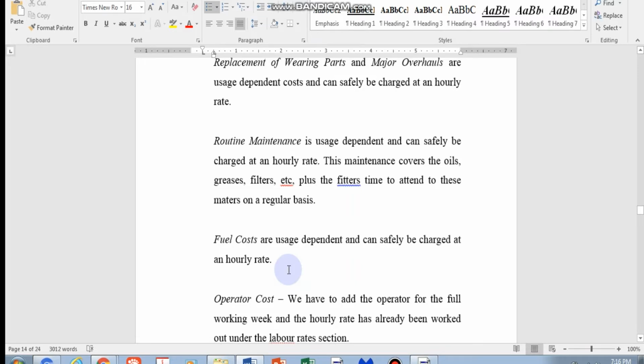So when we talk about estimates, it's actually a very simple formula. It's just the quantity times the rate. The quantity you need to work out from your project. As long as you know the quantity, it can come from the drawings, the BQs, or the design. The quantity is more or less fixed, unless you have extra work or you underestimate some quantity. So the issue with quantity is just making sure it's as accurate as possible. And the rate bit is what I'm talking about in this particular recording.